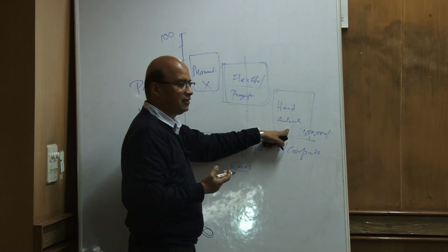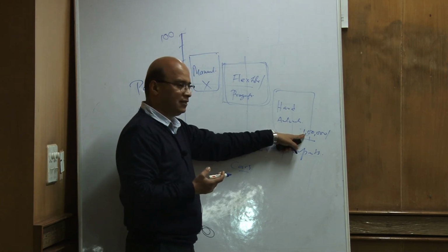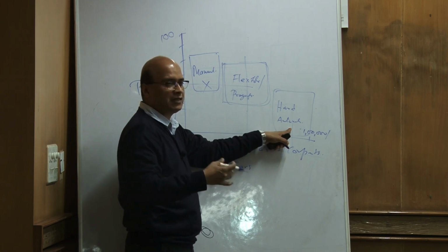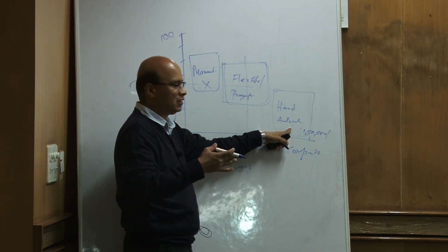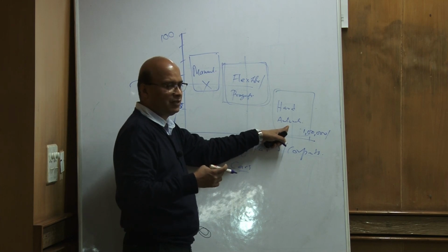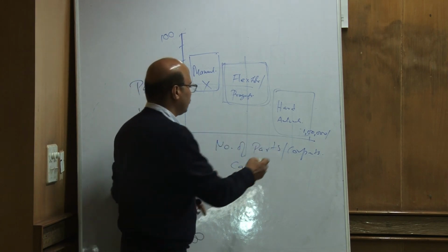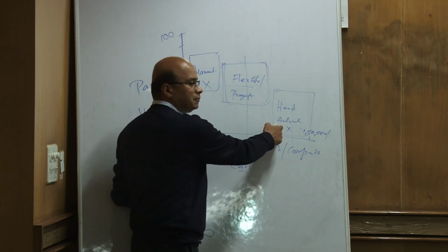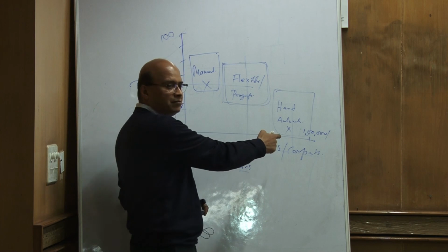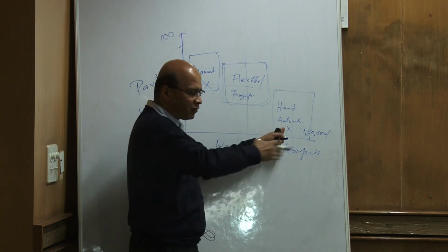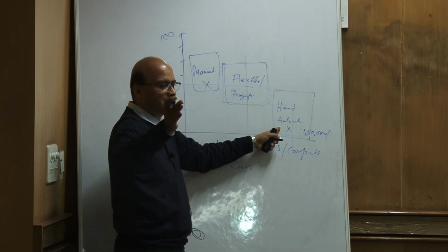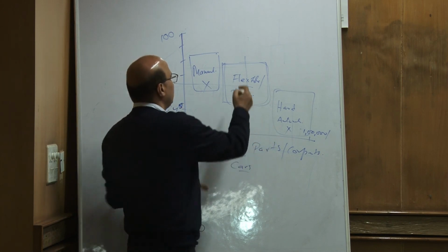On the other side here, the large number of parts are there. So hard automation is much easier here. Something like transfer lines, pick and place, just your normal hard automation devices. Here also robots are not used except for things like spot welding, spray painting. Otherwise, it is not economical again. So simply, if a part has to move from one place to another place, they'll be using indexing or simply transfer devices, but not robots. So robots are only available here.